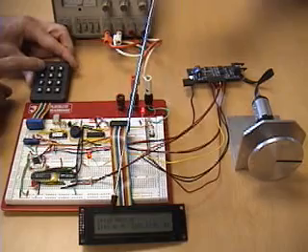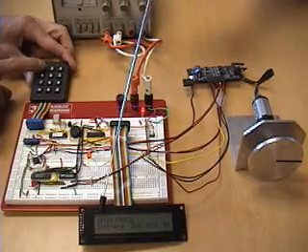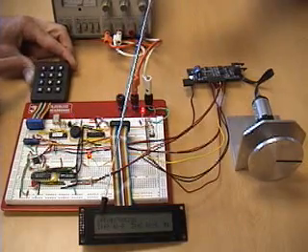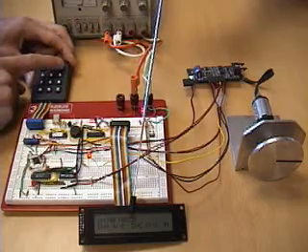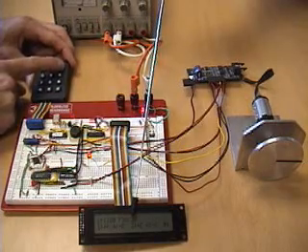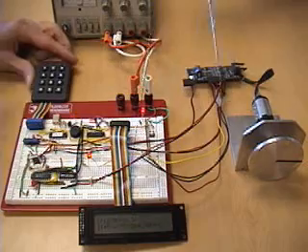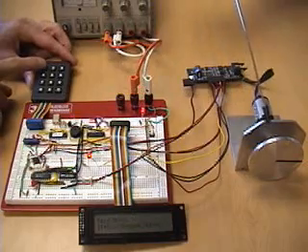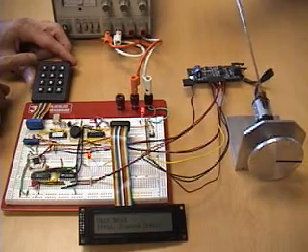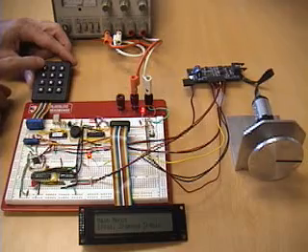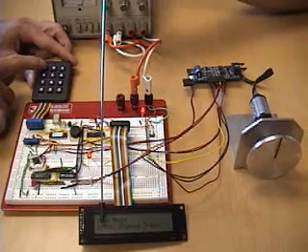The gain we're going to select is 100 for the proportional gain constant, and the pulse width modulation will be 40 cycles. This is an optimal setting that provides reasonably fast speed and very little overshoot. Now we'll go to position control.